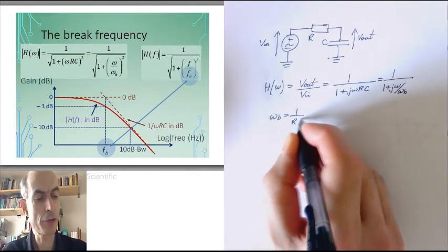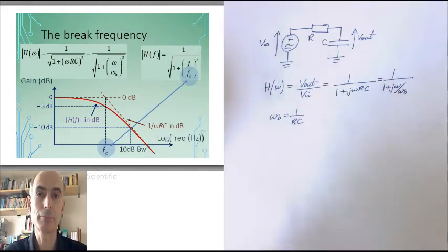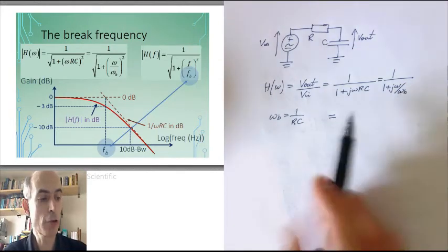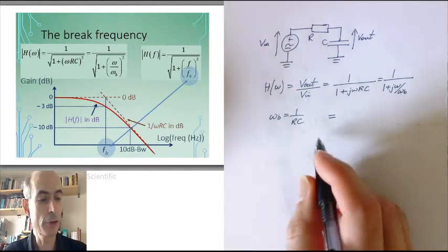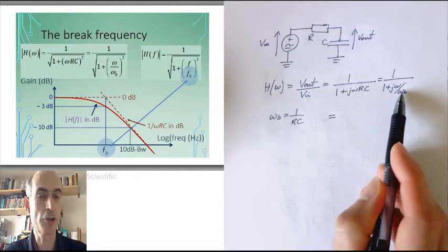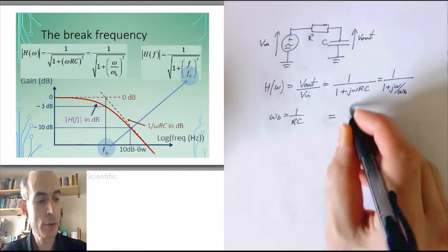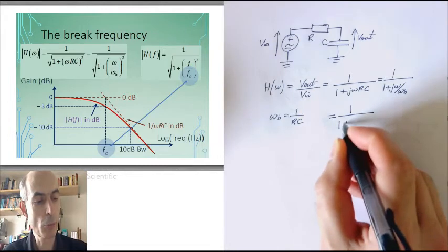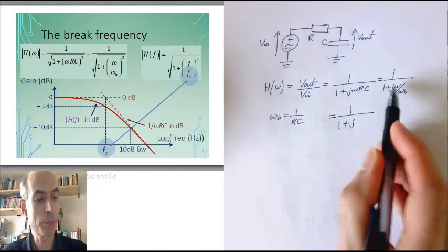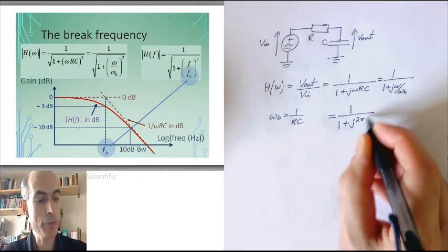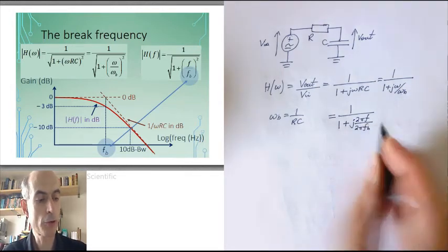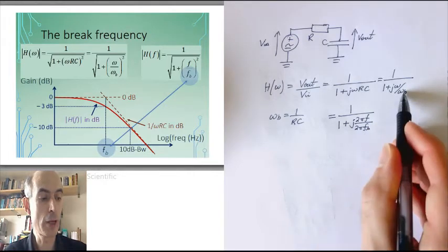And it's a characteristic frequency of this circuit. We can also write this in terms of the frequency in hertz rather than the angular frequency in radians per second by just noting that the ratio of the two angular frequencies is equal to the ratio of the two frequencies in hertz. Or, to draw that out a little more clearly, since omega is 2 pi times f, I could replace that omega with 2 pi f, and this omega b with 2 pi fb, where this is the same frequency only in hertz rather than radians per second.